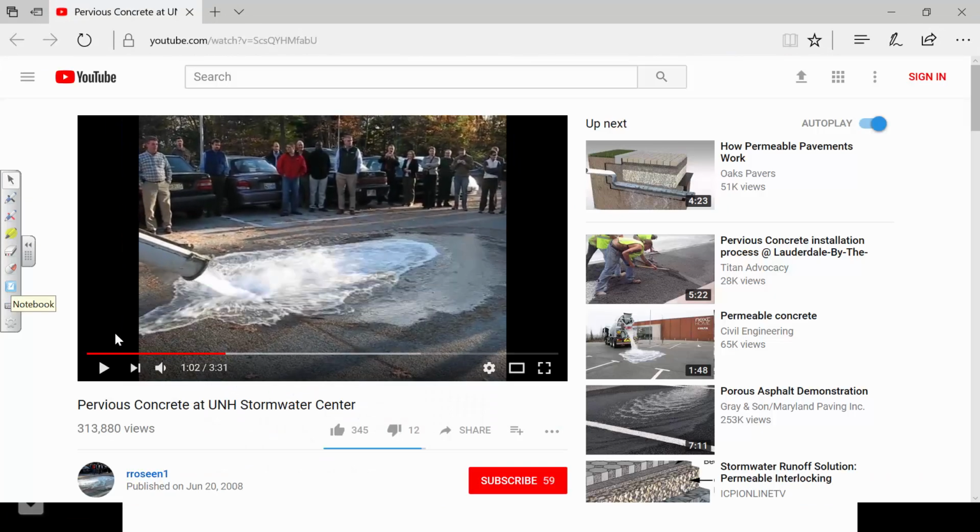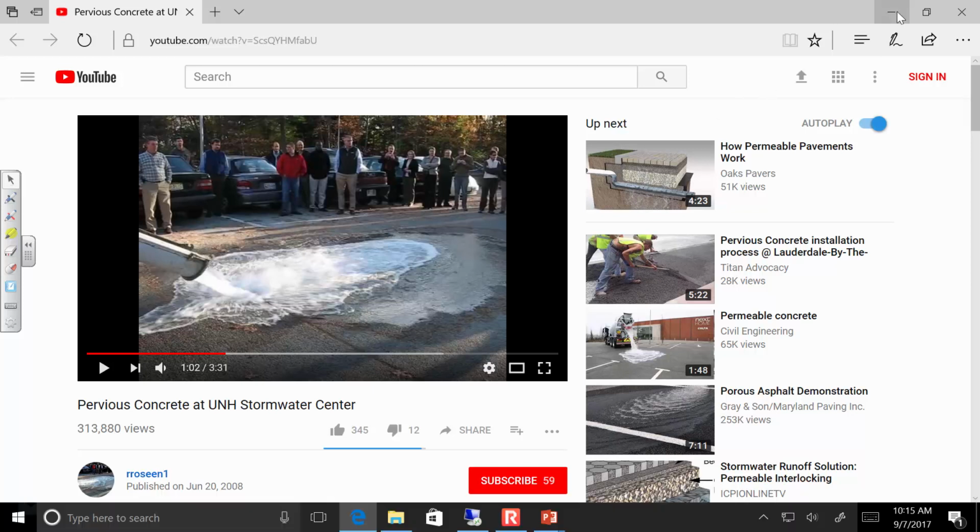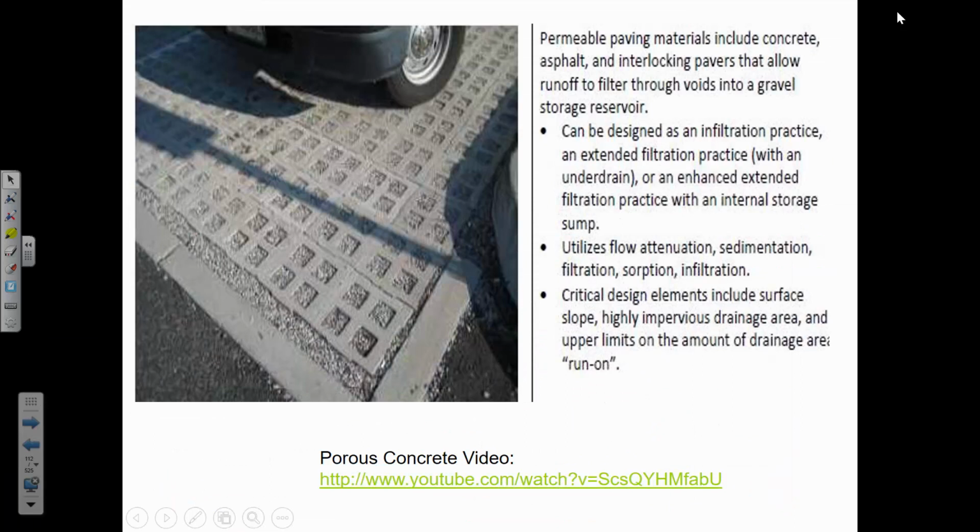It's not expensive. I mean, it's the same ingredients as ordinary concrete. It's sand, it's gravel and just ordinary cement without the sand. But the added expense comes from the expertise and the attention that has to be placed underneath that layer of concrete. And so it would maybe be 4 or 5 inches of this porous concrete, but then underneath you'd have maybe a foot or 18 inches of crushed limestone that's graded really well so that the water doesn't back up into the porous concrete itself.